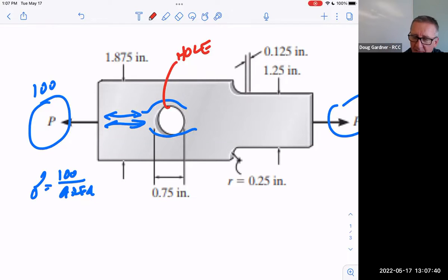There's another spot, and I don't think this is in your book, but that thing is called a fillet. Anything that's rounded off is called a fillet. This right here on the corner of the desk, all of these are fillets. They're rounding a corner off. It's a super common thing to do. It keeps it from breaking. If you bump into it, it'd chip off, and also it allows this plastic edge to go around it and make the corner, which it wouldn't want to do if it was perfectly straight.